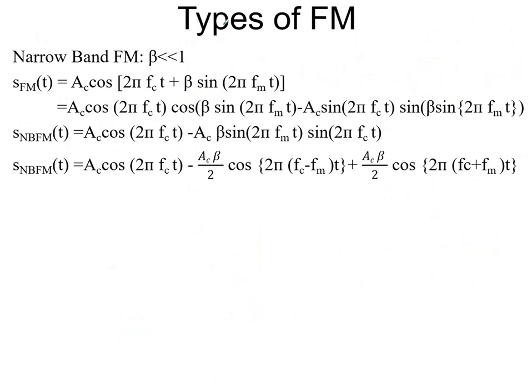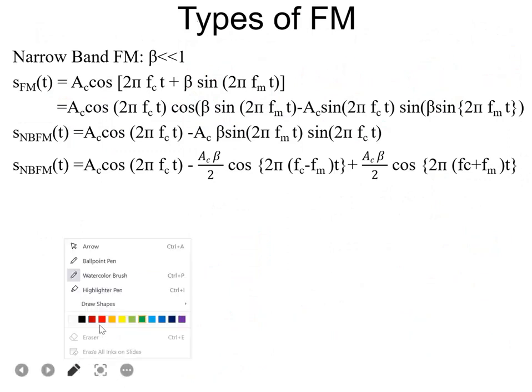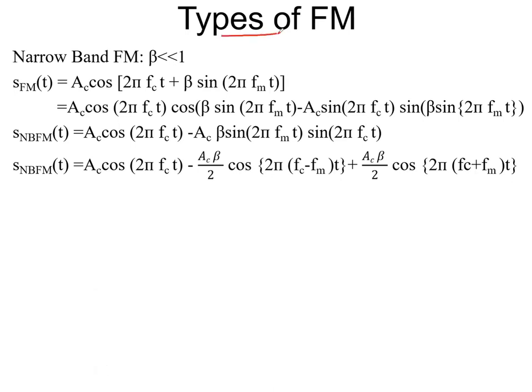Now going to the types of frequency modulation. As we have seen from the graphs, FM and PM are almost similar, except for one small thing. What is that small thing? In FM the integration of the message is there, here in PM the direct message is there.